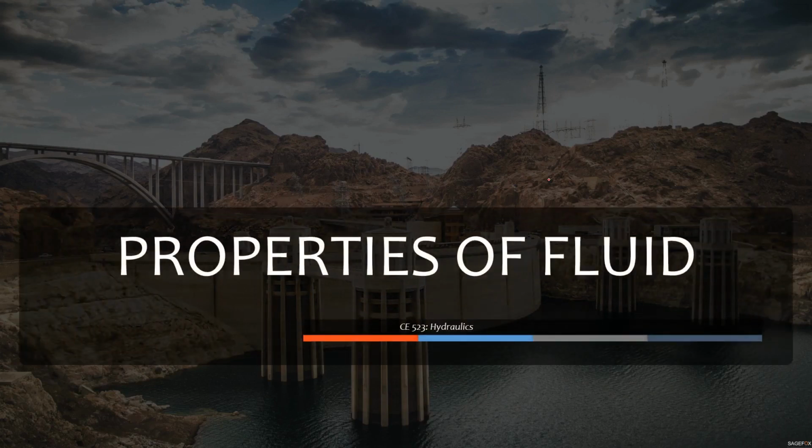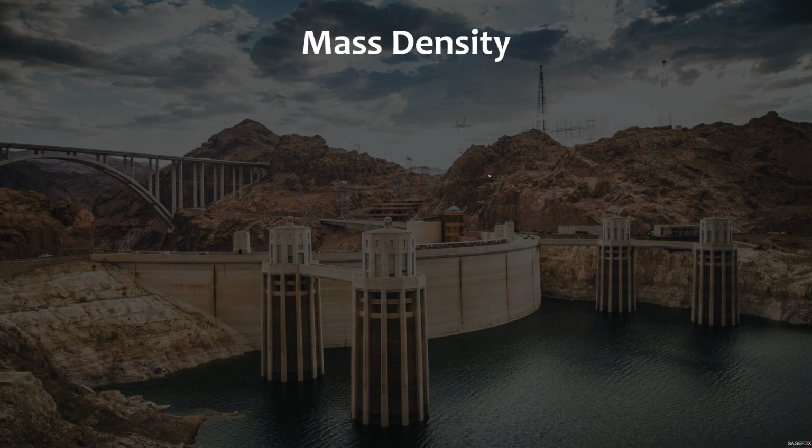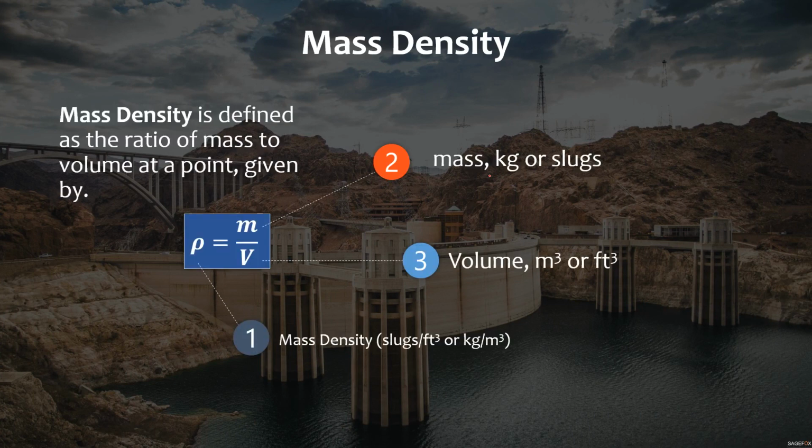So, isahin na natin what are the properties of fluid. The first property that we are going to discuss is the mass density. Mass density is defined as the ratio of mass to volume at a point given by this equation right here. That's mass over volume. So mass can be in the unit of kilogram for SI, slugs naman kapag English system.